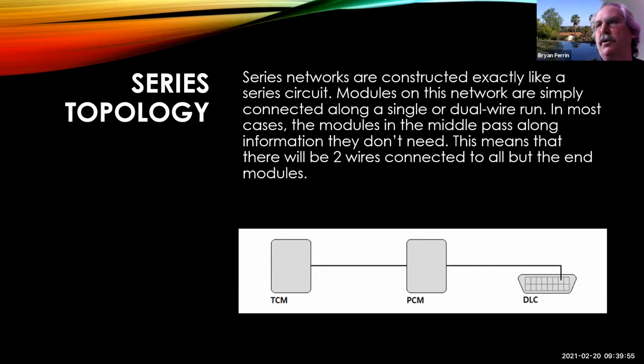So let me hook up multiple test points, because if I have high resistance in the network, I may still have a signal to the TCM, but it might not be anything the TCM recognizes or will respond to. So therefore, let me see if it's the same both places. That's the advantage of having multiple channels on a scope, is we can do that comparison between two points in the same circuit or multiple points in the same circuit.